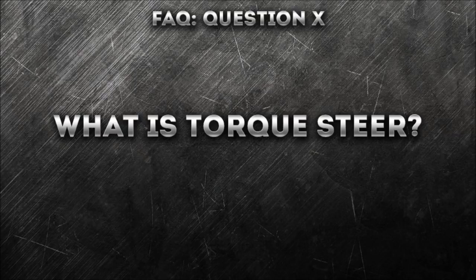Torque steer arises when you have unequal length drive shafts in a front-wheel drive setup. The more torque that is applied at the wheels, the more the steering gets upset and steers into a direction the driver didn't tell it to. As this requires a lot of torque to show up, it is usually a first gear problem. Hashtag first gear problems.